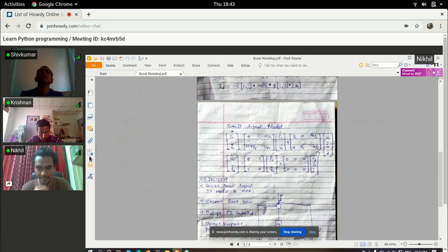So the D matrix again should only be the single column which corresponds to the input that you want to consider. And the same goes for B. So always, you want to map your transfer function between an output and an input. So your output matrix should have the row corresponding to the output variable. Your B and D matrix should have the column corresponding to the input variable. Yes. And for A? For A, I think it should be the full one because it is considering the entire state.